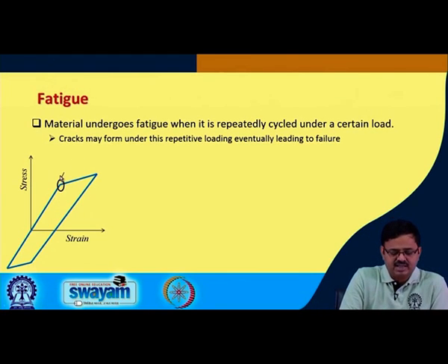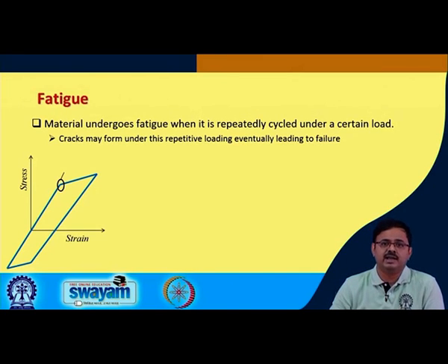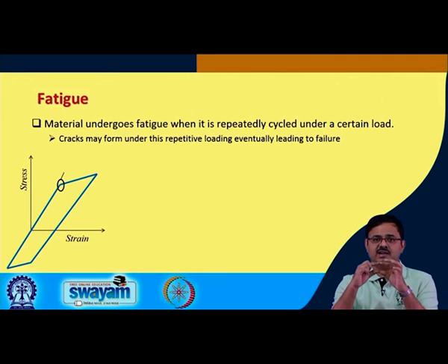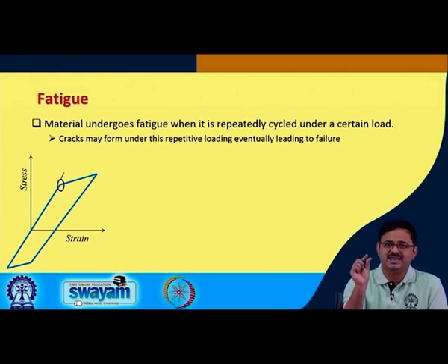Okay. So, this is a classic stress strain curve that you remember, right. We have studied this. So, the first part: what is stress? When you take any sample and put a load, then the load per unit area is known as stress. What is strain? Because of the loading, it will undergo deformation, either it will get compressed and therefore shrink in size, or it will expand or grow in size. If you pull something, the length is going to increase. If you push something, it is going to decrease. And strain is this incremental change in dimension over the original dimension.